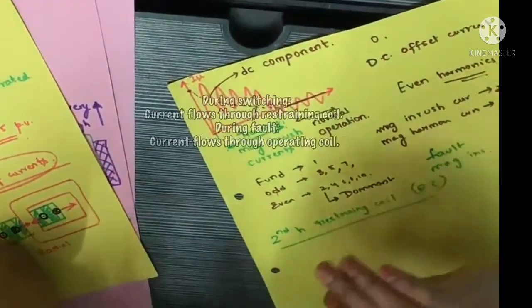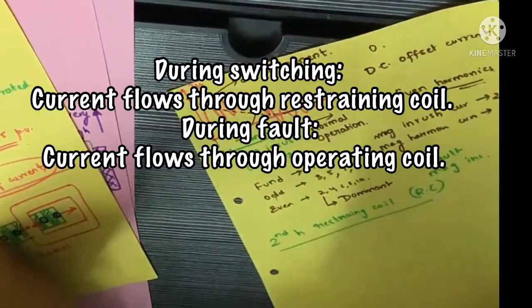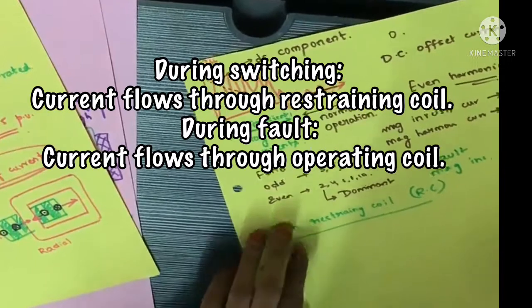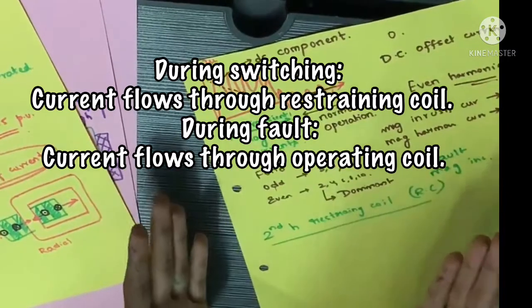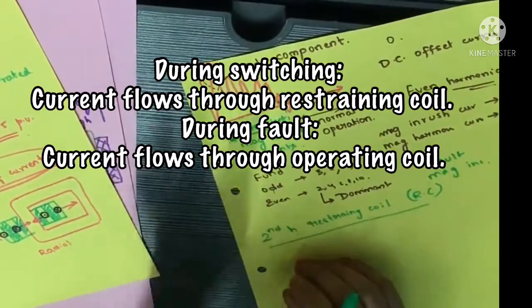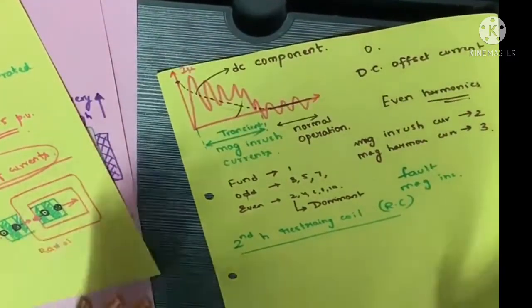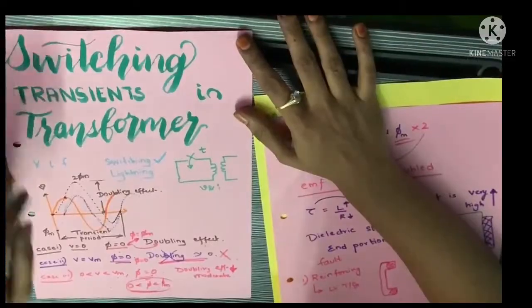But during the fault conditions, the differential current does not flow through this restraining coil. The differential current flows through the operating coil and it trips the circuit. So if the restraining coil is activated, there is a negative action on the operating coil, that is no operation of the circuit breaker tripping. If the restraining coil is inactive, that is in case of fault conditions, the operating coil acts, that is the relay operates to trip the circuit. So this is how it happens in the transformer when there are switching transients. I hope everything is clear. Let me give it a glance.